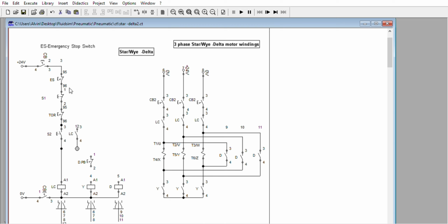We are going to remember, always start with the start stop control. You can also have the connections written here. So this is for delta. The Y: line 1, T1, T2, T3 and 4, 5, 6 connected or tied together. The delta is 1 and 6, line 2, 2 and 4, 3 and 5.